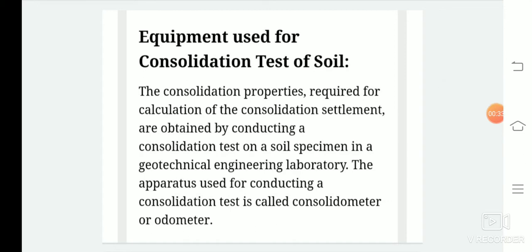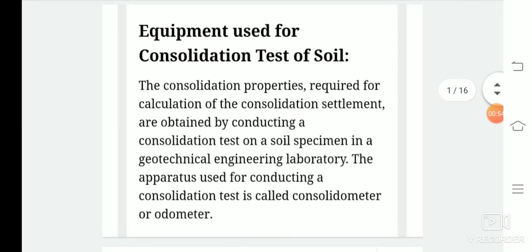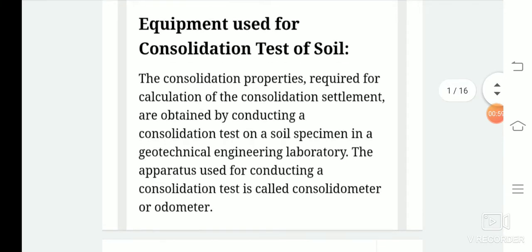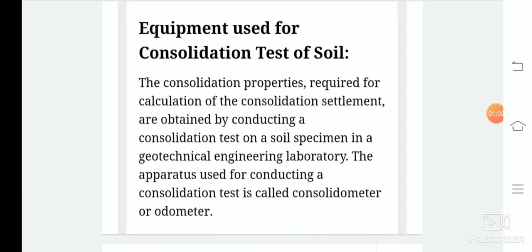of. Normally, the consolidation test consists of applying pressure on a thin soil sample in increments and keeping each pressure increment for a sufficient amount of time until the consolidation of the soil specimen, while the measurement of the vertical deformation of the soil specimen due to expulsion of the pore water carries on. Main consolidation parameters such as the coefficient of compression, the coefficient of volume change that we have discussed, as well as the coefficient of consolidation, can be determined from this consolidation test under a certain pressure increment.